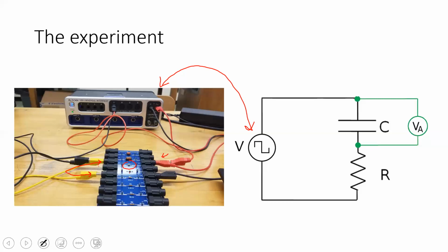And you can see here, right here on the board, you might even be able to read that in the picture, that is 47 kiloohms. That is my resistor. And then I'm going to go out of my resistor and back to my function generator. So then I've completed this whole loop that is shown on my schematic.